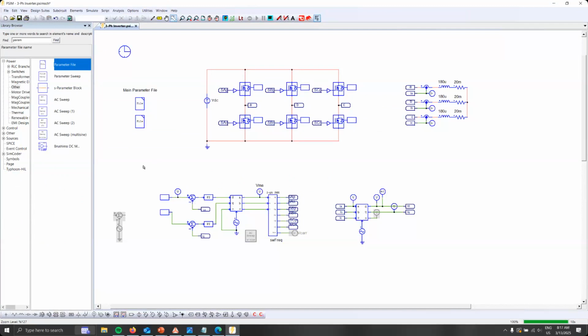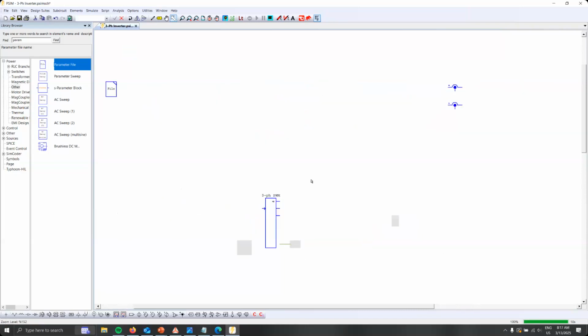First, let's explain what's happening here. We have a three-phase inverter, pretty straightforward, with an RL load. Here at the right, I have designed some PI controllers for this inverter. As we can see, we're controlling in the DQ frame, giving the references to the inverter, and then generating the PWM waveforms. So on that end, pretty straightforward.